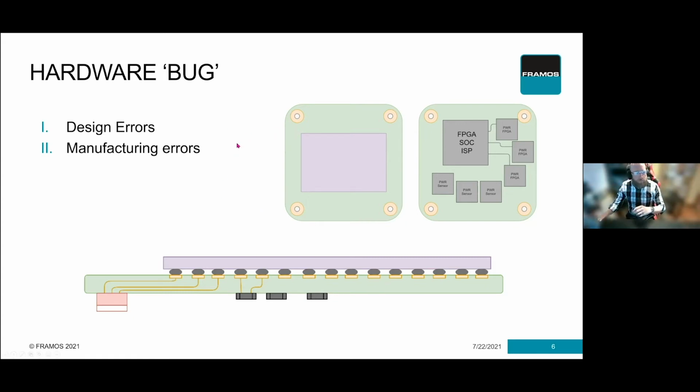The other thing within the design errors is sort of design intent. Especially when you're moving from, let's say, a prototype into a mass production device, we're changing a number of things. So we're making it smaller, we're meeting the new physical sizes. So we might have to do things like remove certain passives or move those passives away. And because we've done that, the system may operate in a different fashion.